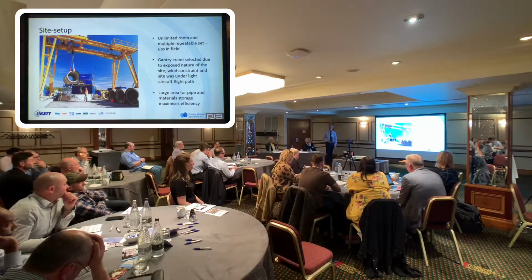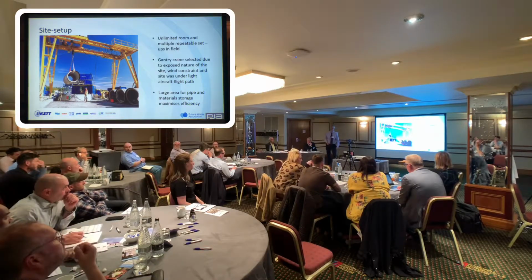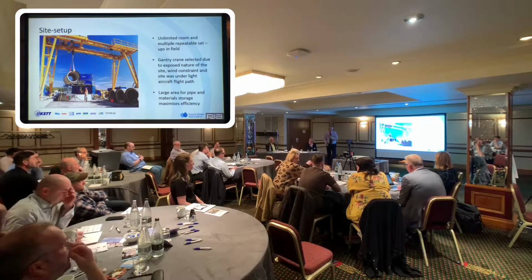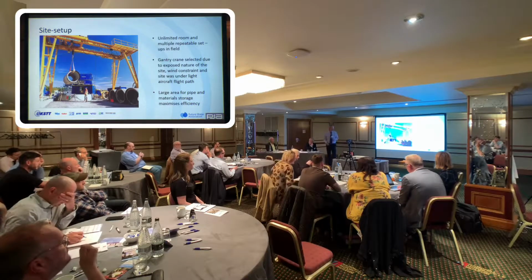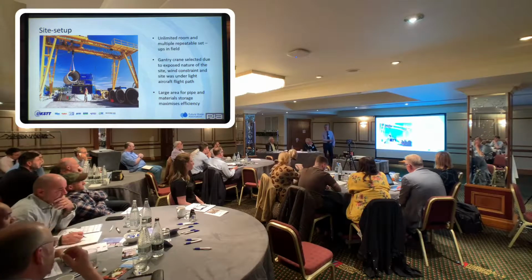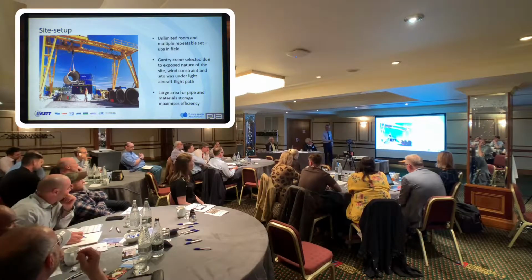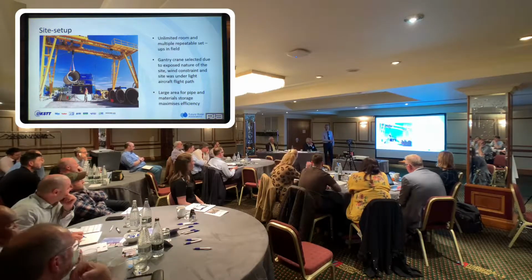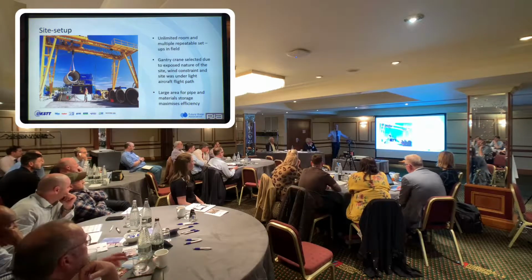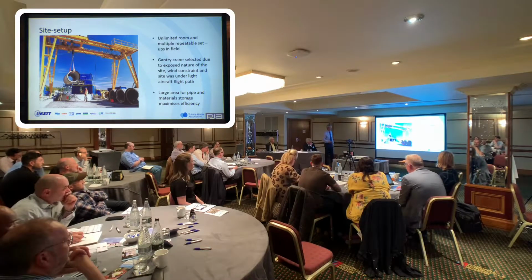I was just going to ask, is that a temporary load you have to account for, having that container in the shaft? Not really. It's about 5 ton. It weighs very little in terms of loading, and that shaft was sunk as a casing, so there's a big donut of concrete around it, plenty of bearing, so you wouldn't really need to consider that.